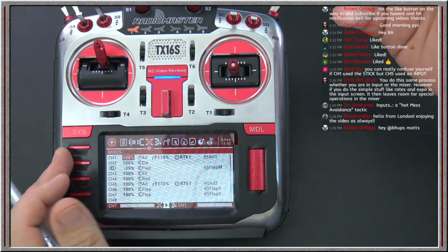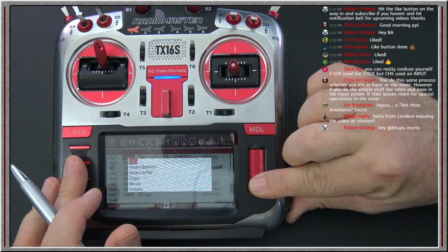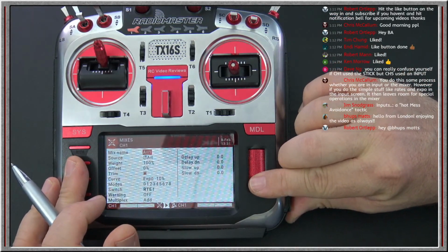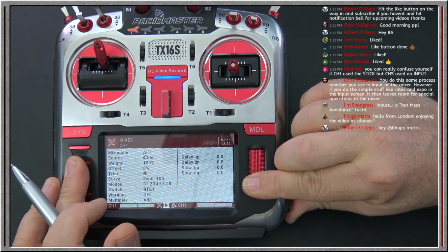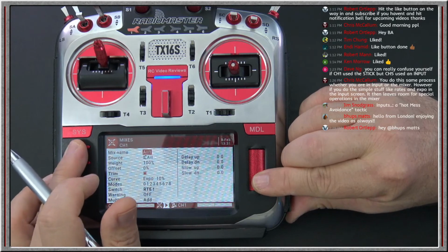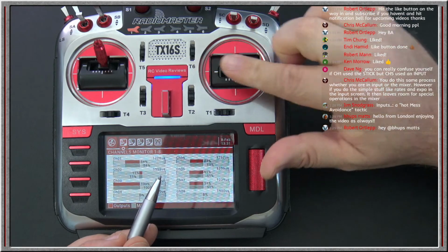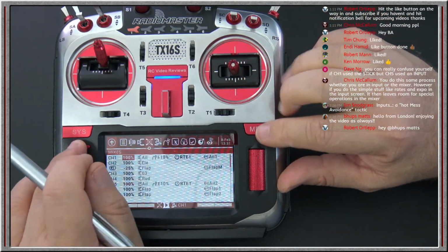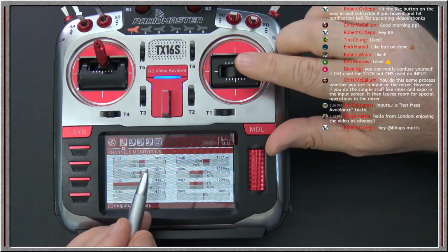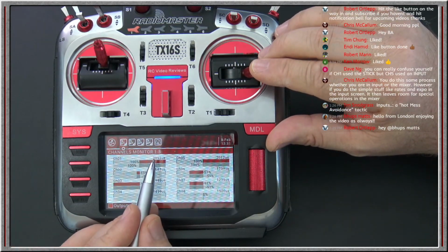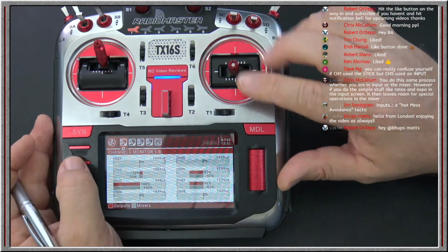The last thing we'll do is we'll take a look at the outputs. So on the outputs, oh no, let me change my aileron back to the source, the input rather. There we go. Okay, so if we look at the monitor and we say, okay, I've got left, I've got right, everything is copacetic there. Now, let's say that in Betaflight, I'll bring this monitor back up. Let's say that in Betaflight, I'm putting out 2012 microseconds and I only want 2000. Well, the place to deal with that is in outputs.